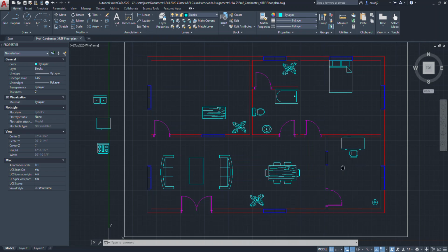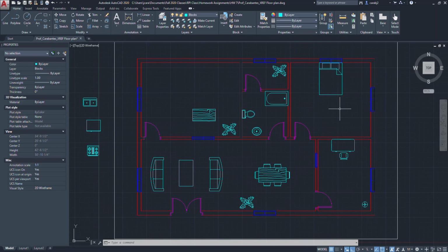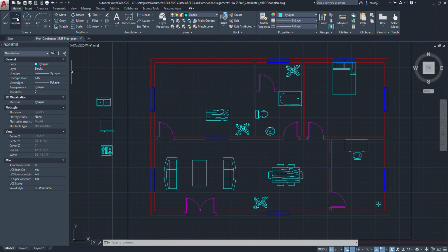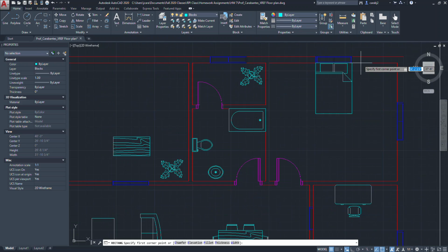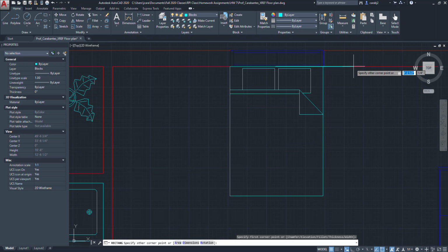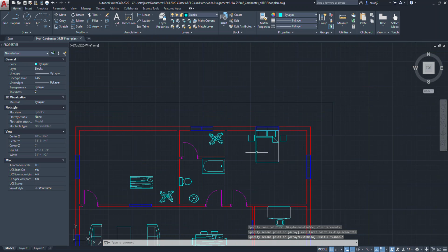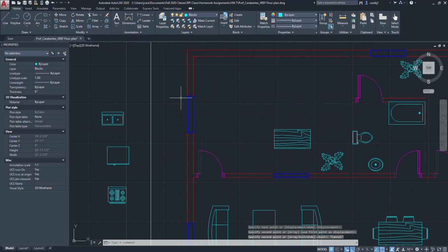Okay, so I have most of my floor plan populated with some furniture. Like I said before, if you want to add furniture, you can actually draw it yourself using the polylines or the rectangle tools to create any blocks that you don't see in the AD center. So you can make little nightstand tables if you want to. Just add some furniture there. And if you want to create kitchen cabinets, you can do that as well, or countertops. Countertops are usually 2 feet wide, and then you can make them as long as you want, down to the wall if you want to.